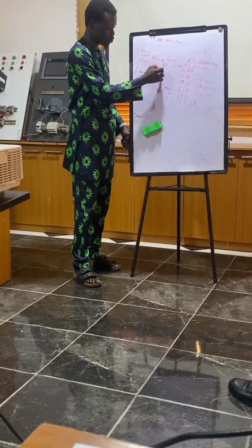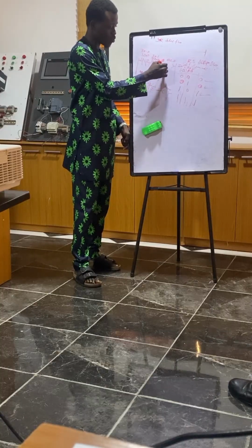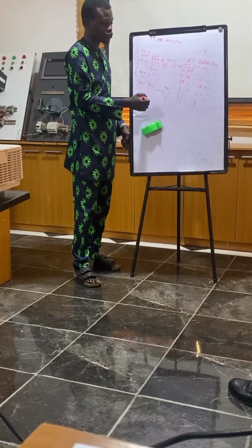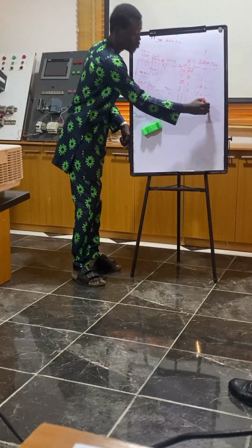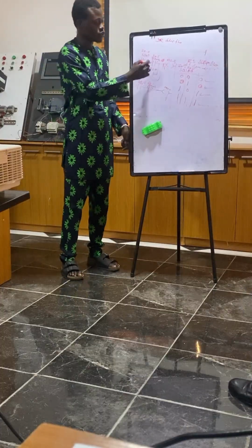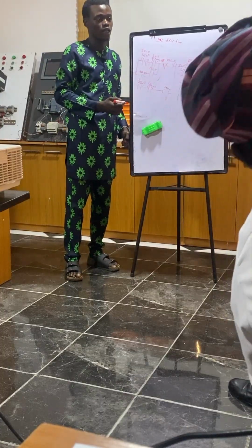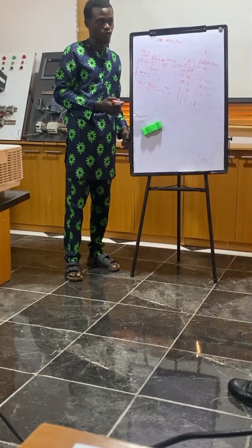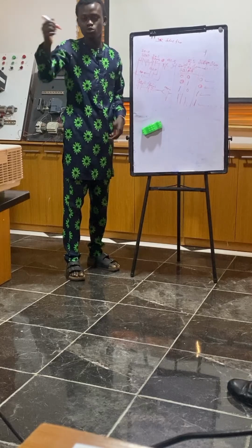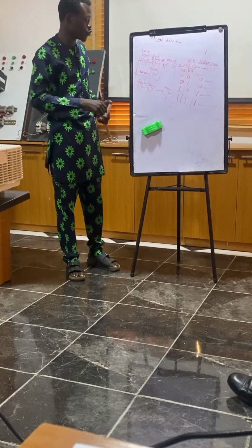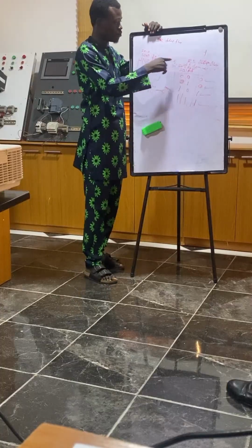This has bypassed the whole system. So at this point, you have 1, which is why your Q2.0 will come on. So this forms an RS flip-flop. Okay, so let's look at somebody else's program to confirm.